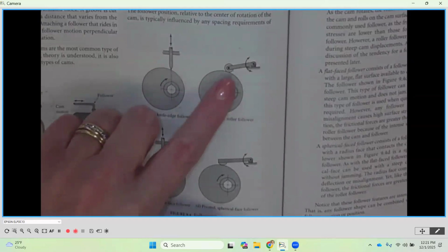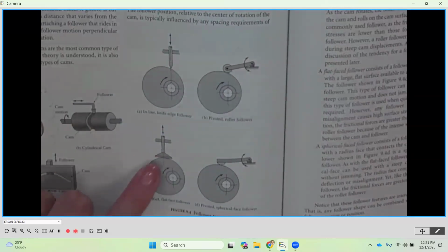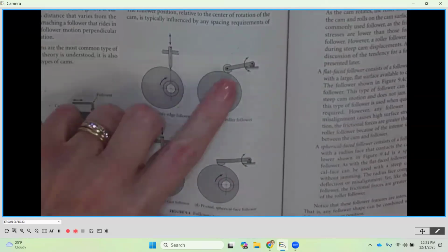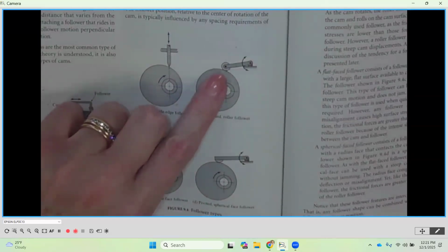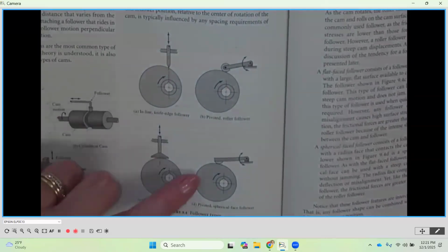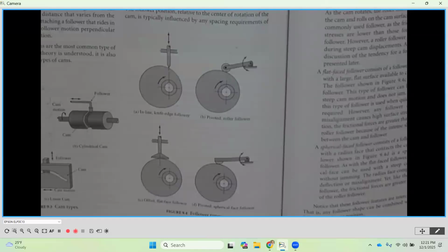Additionally, the type of contact that you have with the cam is going to depend on the application. When we have things that are more high speed, a roller tends to be the one that we put in contact. If they're low speed, then the friction type of application is going to be what we use.